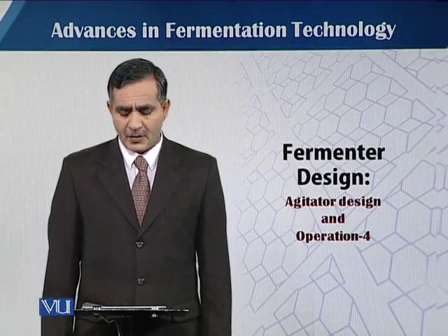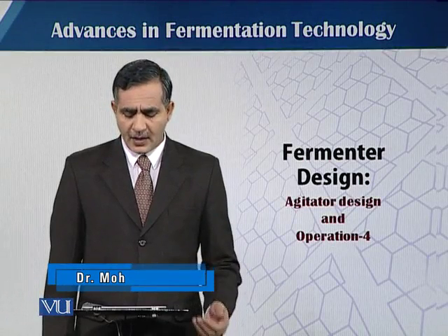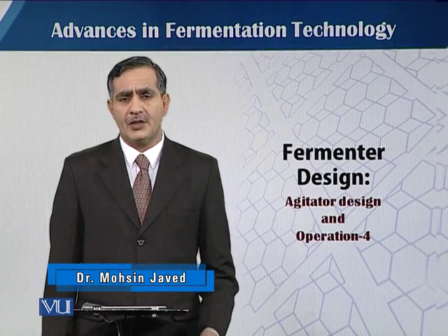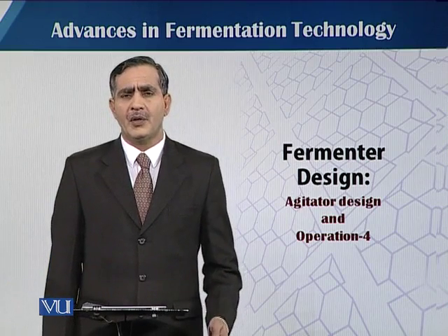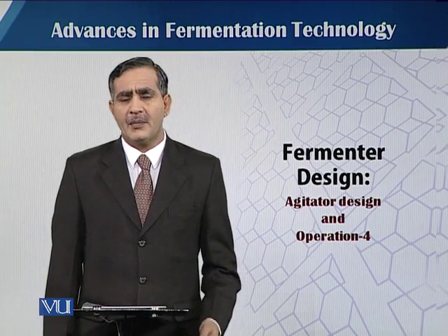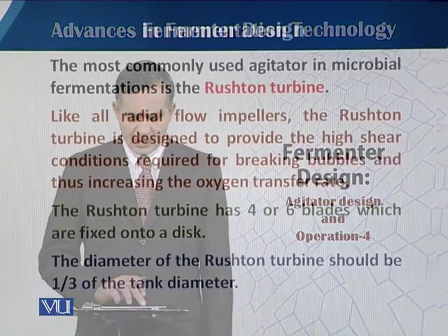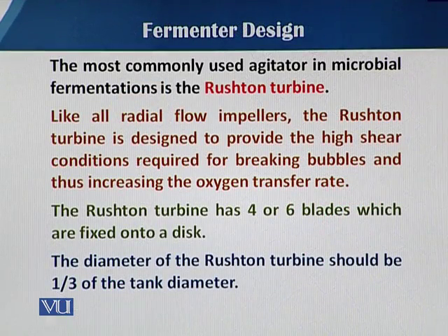In this module, we will talk again about agitator design and its operation. As we have discussed in our previous module about the radial flow impellers, in this module we will focus upon Rushton turbine impellers. Actually, the Rushton turbine impellers are just like the radial flow impellers, with only a small difference. Mostly in fermenters, they are fabricated and designed with Rushton turbine impellers.